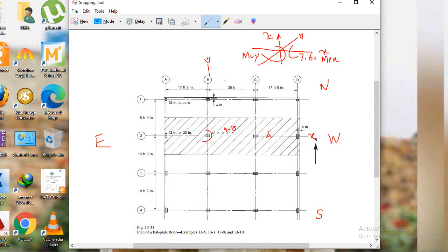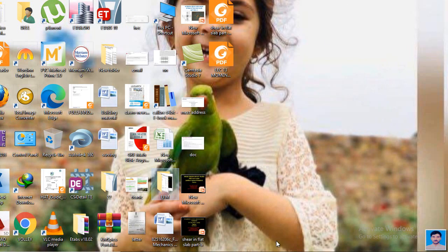Let's say we assume we have no lateral loading, so then we find the vertical shear, which can be easily determined by finding the tributary area and multiplying it with q. You get the vertical shear. So you get your VU, your PU, MUY, MUX, and then go for the design of the biaxial column, as I already discussed in lecture number 7. So this is the procedure for how to calculate the moments.